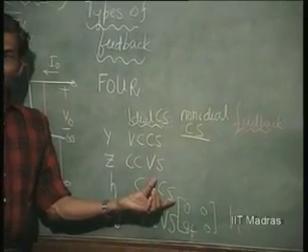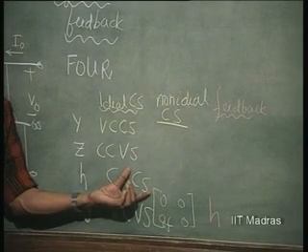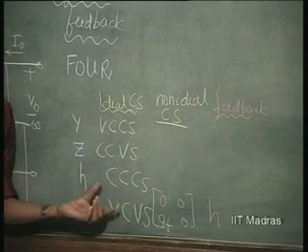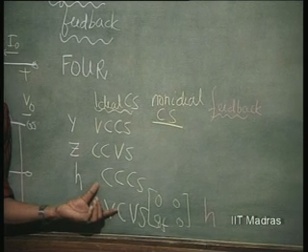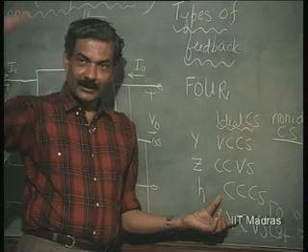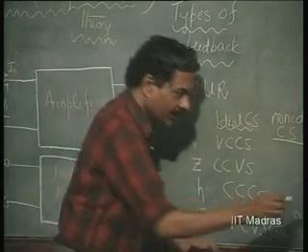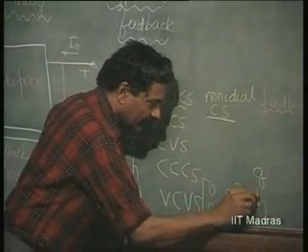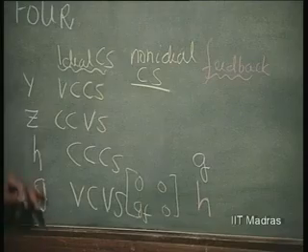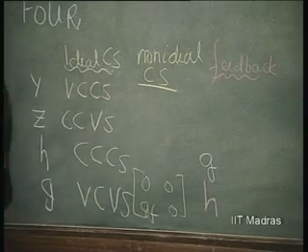It is a current source, its output impedance should get boosted up. It should become a short circuit at the input, output impedance should increase. That means things should be in shunt at the input and series at the output, which means it is G feedback. This was H feedback. In order to obtain an ideal current controlled current source, I must apply G feedback.